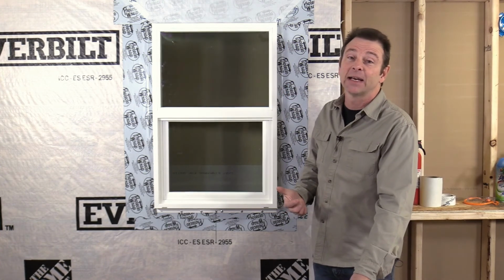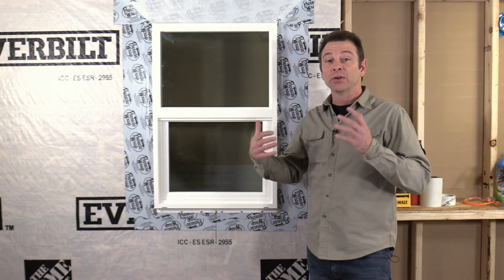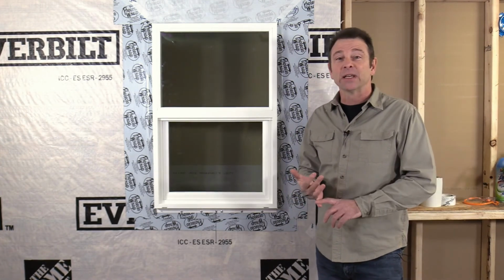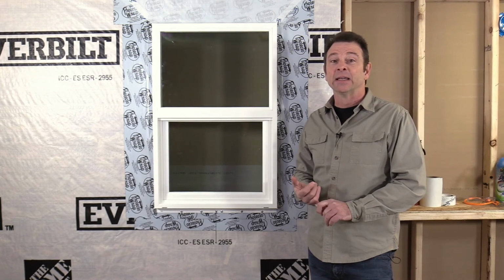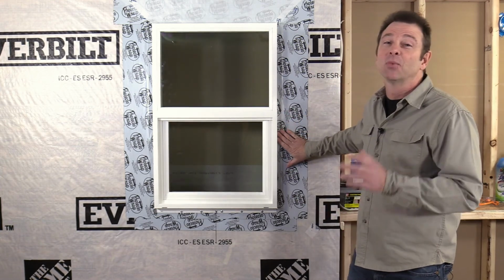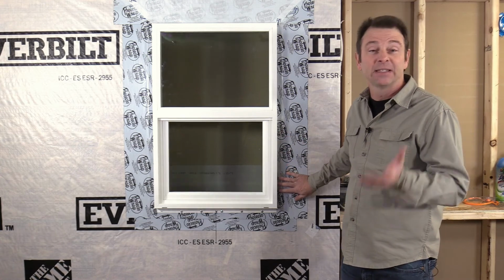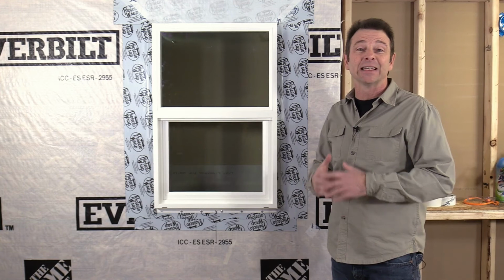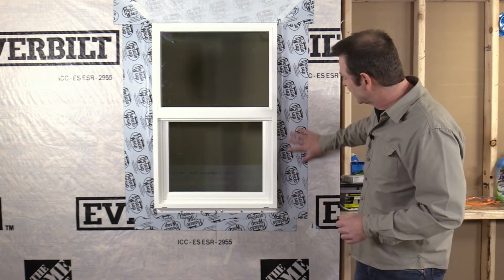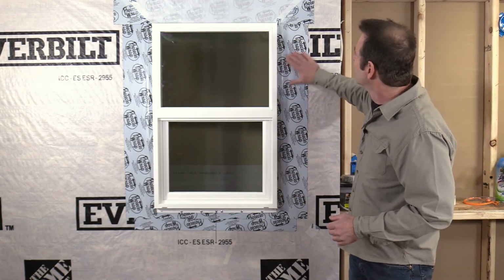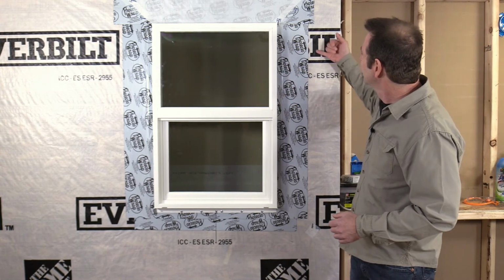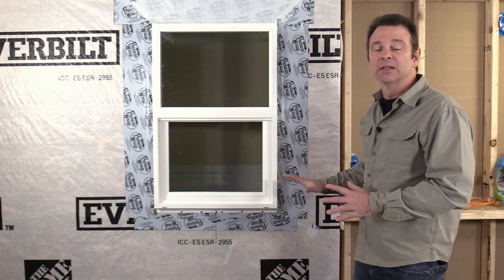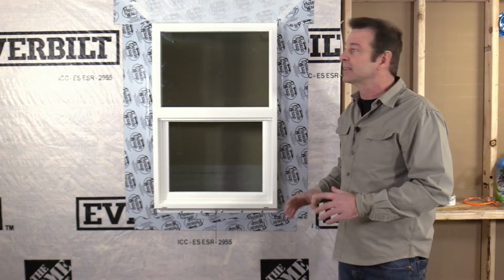If you show up on site, and I've seen this, where you can see a whole house where this stuff is peeling off, you can be sure that something wasn't done right. And if this fails, then we have lost half of our sealing capability of this whole window installation. And a window that leaks is no good. So keep in mind, this should be nice and flat, no creases or wrinkles, no way for water to get in, fully adhered, and it should look good. This should be a nice, neat installation.